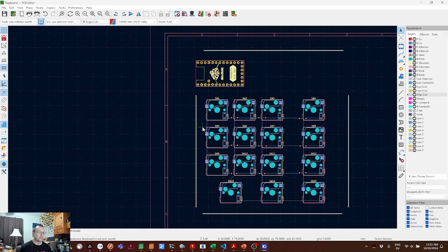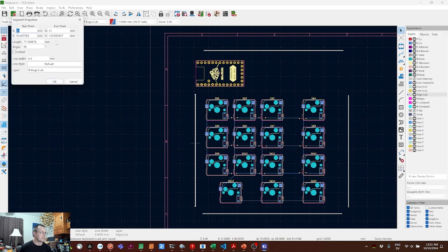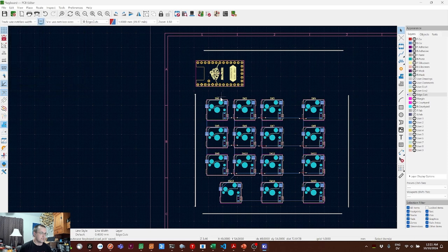Now, to make this a nice rounded rectangle, unfortunately KiCad doesn't have a lot of drawing tools available, but we're going to use what we can. With this 1mm grid selected, we're going to drag this edge to snap it to a grid line. And we're going to double click it just to check. X is 31. I think the endpoints, the Y is not quite set yet. So you can drag those to give it nice sharp corners. You may notice that the line doesn't stay vertical though. Fix that by hitting Shift Space while you're dragging, and now it'll stay nice and vertical or horizontal. So we'll drag these corners out until they meet. And that'll give us a guide point for where we're going to put our corner arcs.